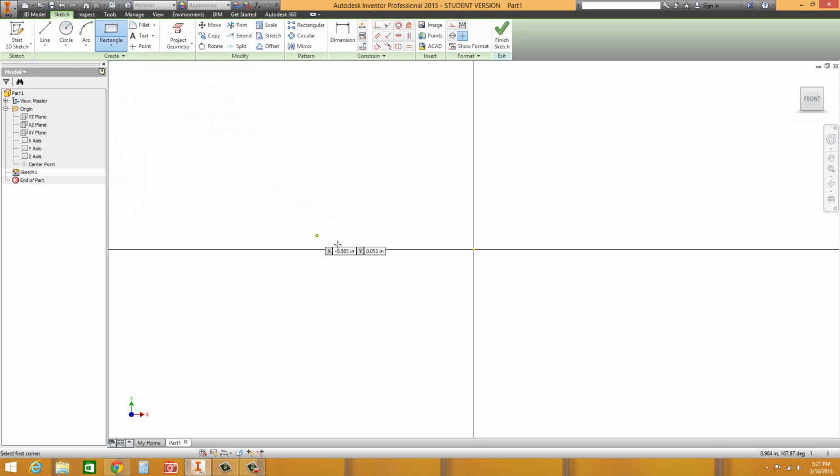So click on that. Now move your pointer until it locks into that origin. Because my screen background might be a little different than yours, I get a little green dot that indicates it kind of snaps to it. When you get that, you just simply click one time. When I say click, you click once with the left mouse button. Release it and move this up.